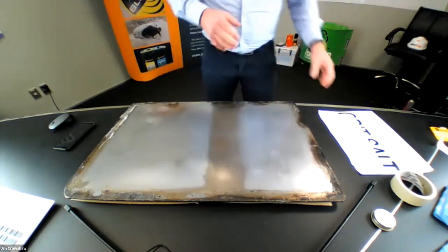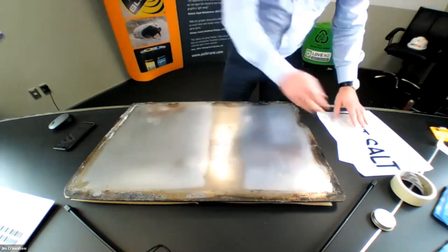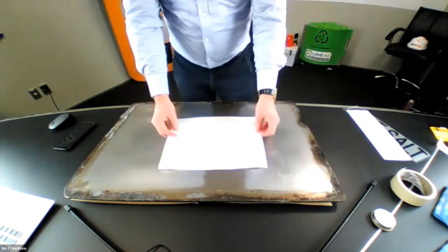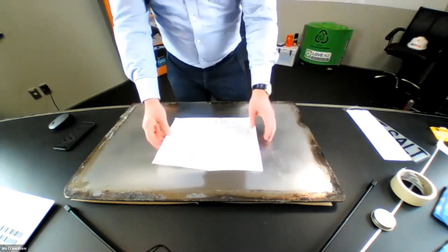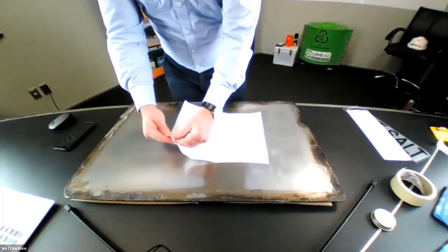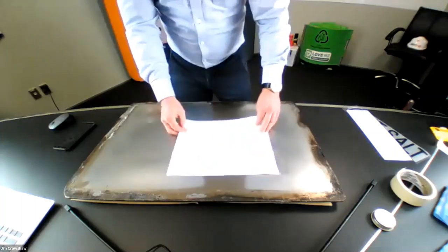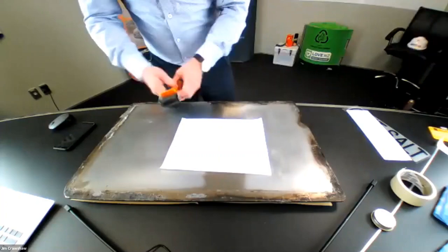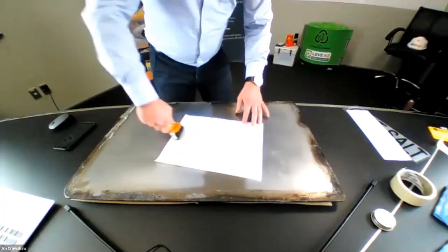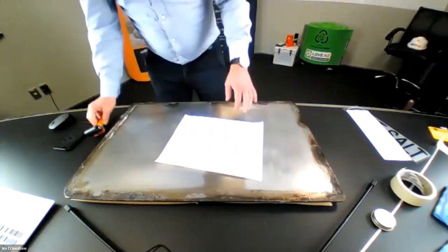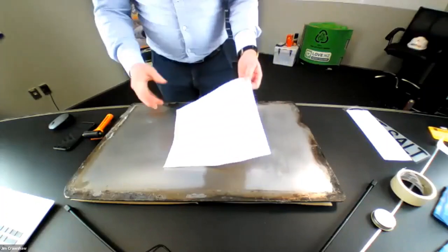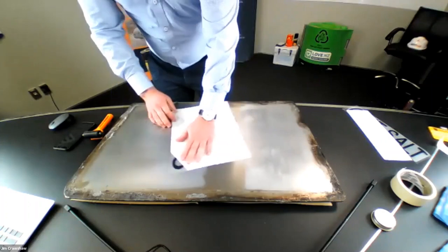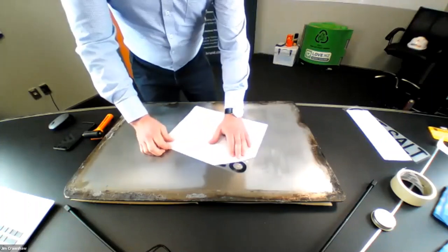Okay, next up, I'm going to run through the graphic applications for you. Starting off, I'm going to start with the type 2 InMold Original. This is the type where we talked about not peeling the tape straight up. We talked about flipping it over this way. So I'm just going to give it a quick roll for a start. I'm rolling over this tape because, especially if it's been in storage for a long time, that tape can tend to separate from the graphics. So it's just strong enough to hold it in place while we transfer it onto the mold.